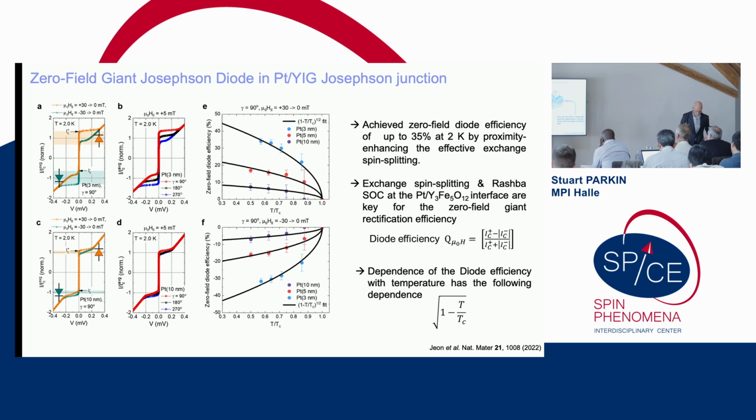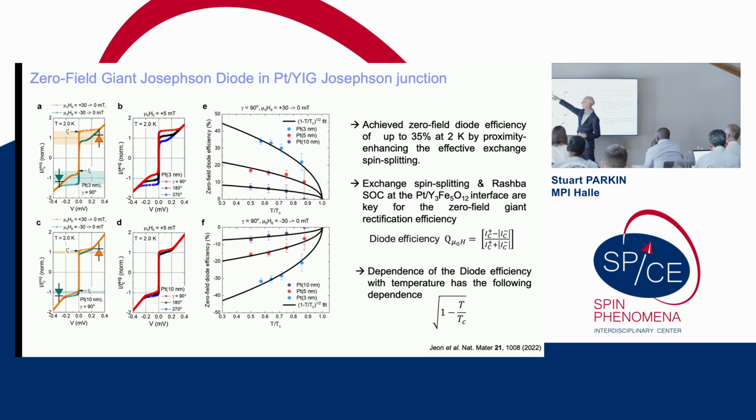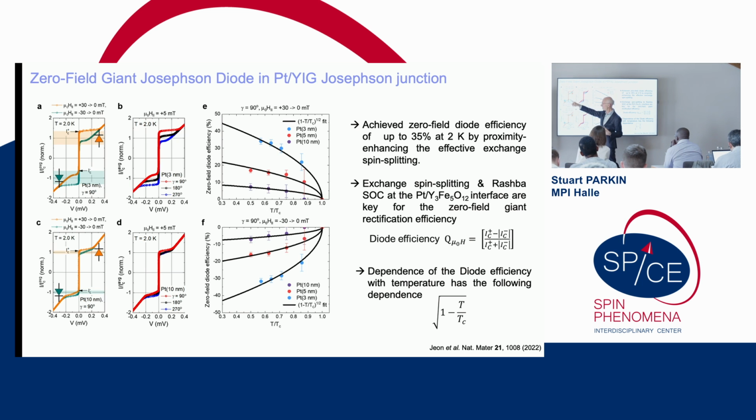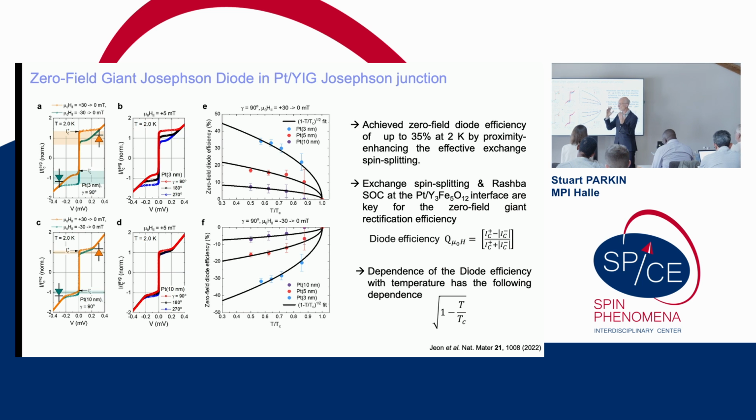Then on top, the niobium will make the platinum superconducting by proximity, and these two proximity effects combine to give a diode effect. That means if we measure the critical current above which we suppress superconductivity, you see the voltage is 0, then it becomes finite. This current flowing in one direction is different from the critical current flowing in the opposite direction. This can then act as a sensor in our racetrack. If the domain points in one direction, we will see a supercurrent flow in the opposite direction. We would not otherwise. This difference in critical currents is up to 45% at 2 degrees Kelvin.